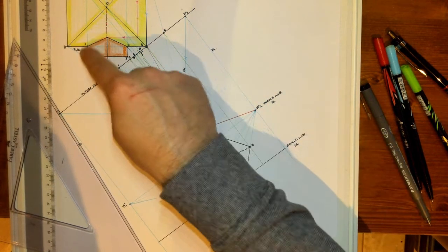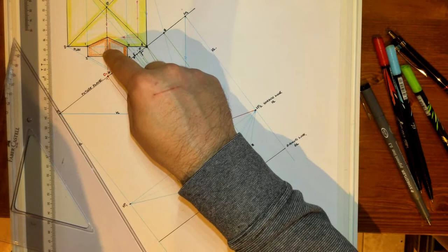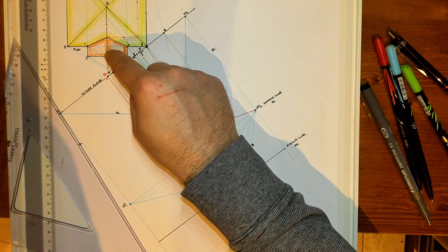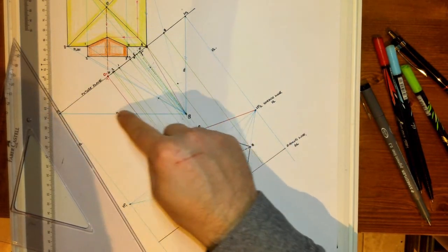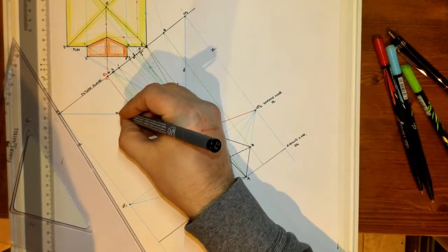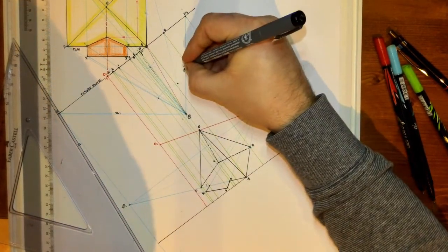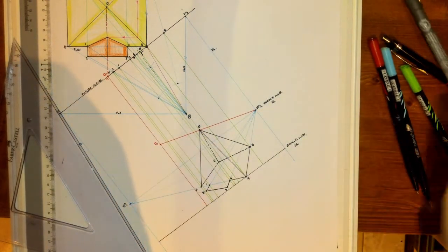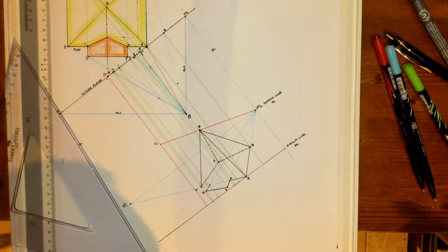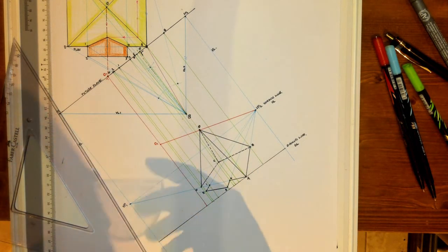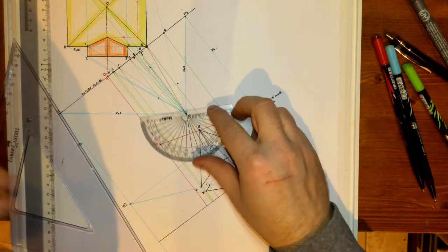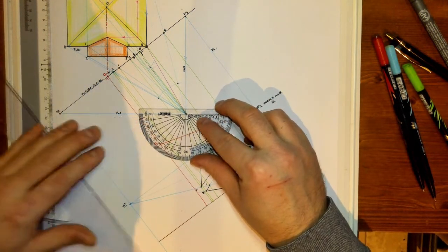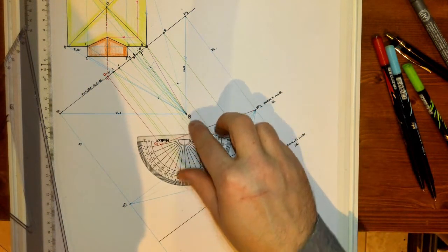So as you can see, this surface here that we're trying to form using the auxiliary vanishing point is facing the vanishing point here, and I'll distinguish that as vanishing line 1, and this one is vanishing line 2. Okay, so vanishing line 1, this is what we do to find the auxiliary vanishing point: we take our protractor now. The angle in the question was 40 degrees. So turn your protractor. Well, you can do it this way.